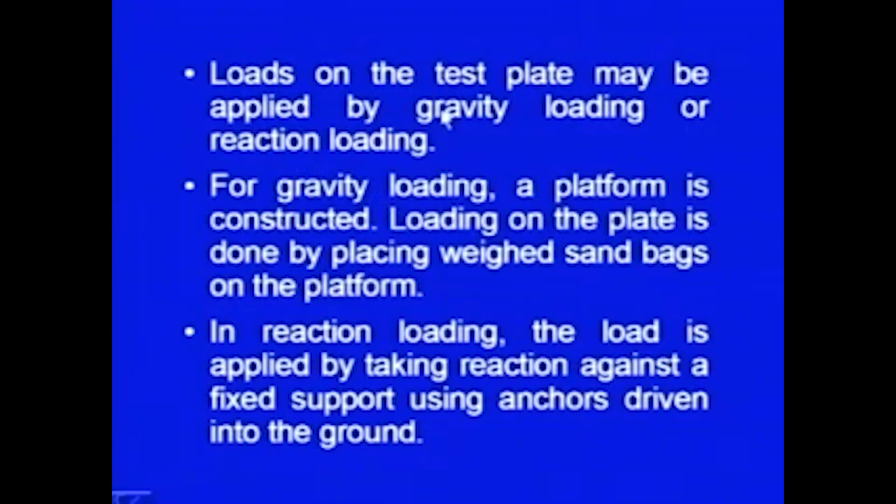The loads on the test plate, as I told you, what we are going to do is simulate the actual field conditions. In actual field, the foundation is subjected to incremental loading. So, loads on the test plate have to be applied, and we can have two types of arrangements to apply those loads. The first kind of arrangement is gravity loading, and the second kind of arrangement is reaction loading.